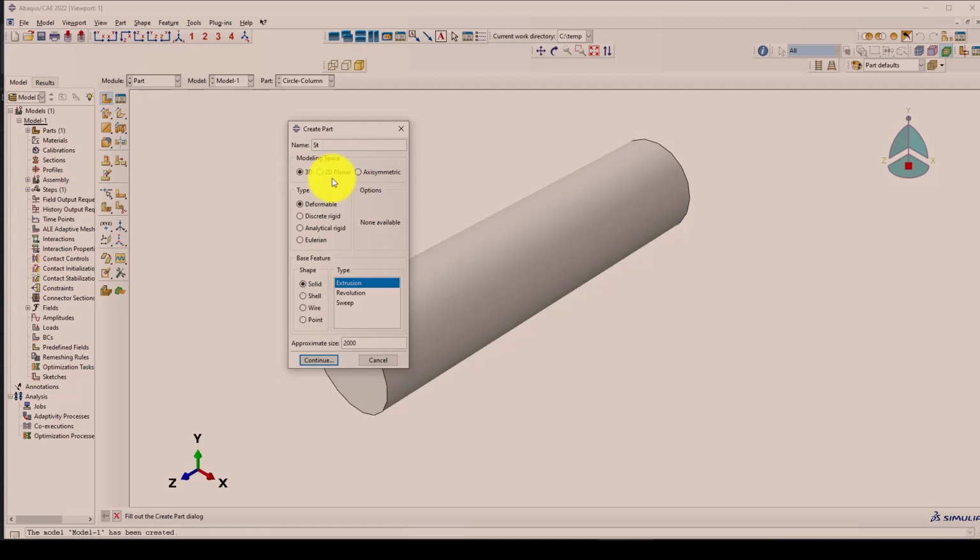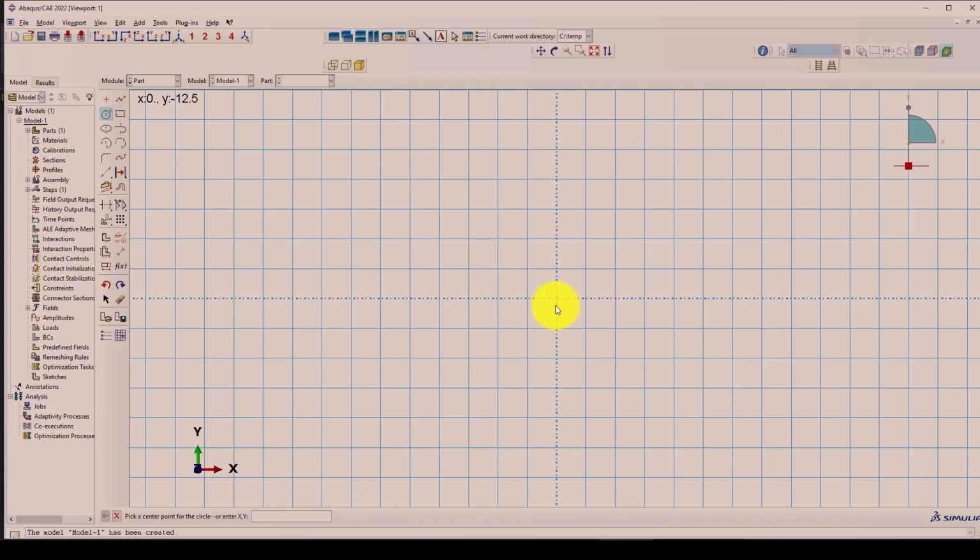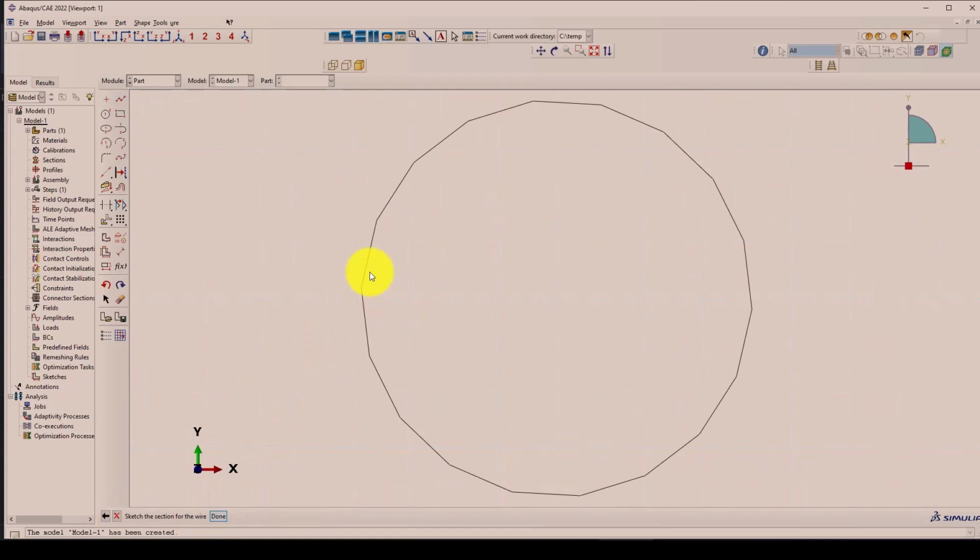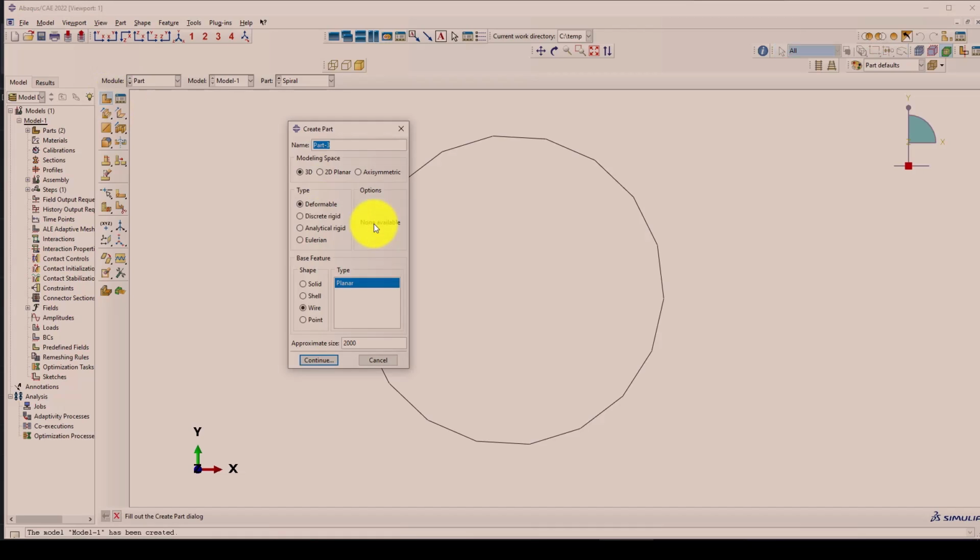Next I want to call stirrups, or sorry, this will be spiral. We should call it spiral, and we're using wire and planar. Now I can again use circle 0 0. In the previous one it was 250, so we want 30 millimeter on both sides, so then it becomes 220. So the third part is done, and the spiral is done.